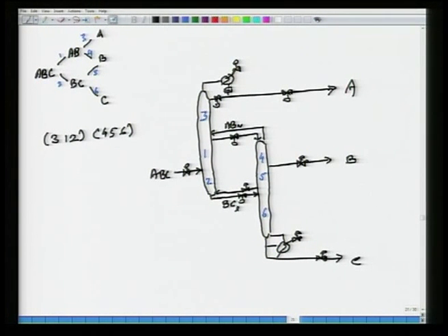And again if I look at, well, did I miss a few valves here? 1 2 3 4 5 6 7 8 9 10, that's excluding the feed there are. So excluding the feed there are 9 valves, 3 levels need to be controlled, 1 2 3, level controllers 3, 1 pressure needs to be controlled, degrees of freedom again turns out to be 5.